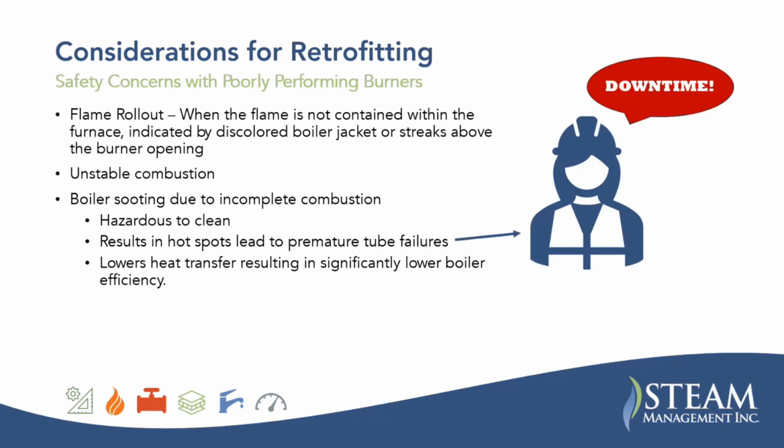Safety concerns with poorly performing burners. So we mentioned flame rollout. That's basically when the flame is not contained within the furnace, and it's indicated by a discolored boiler jacket or streaks above the burner opening.